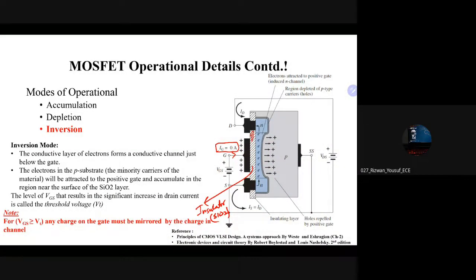तो अगर आपने देखा होगा, हमने BJTs में input characteristics पढ़ी थी. Input characteristics हमने कहा it is a plot between input current versus input voltage. Okay, so I input versus V input. वहाँ पे हुआ करता था IB input current and maybe VBE input voltage. क्योंकि यहाँ input current हमेशा 0 होती है, तो यहाँ input characteristics नहीं होती है.